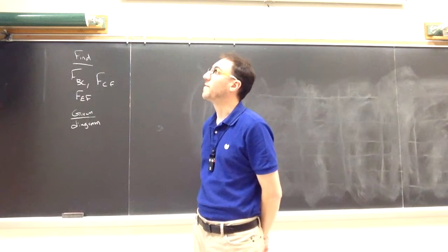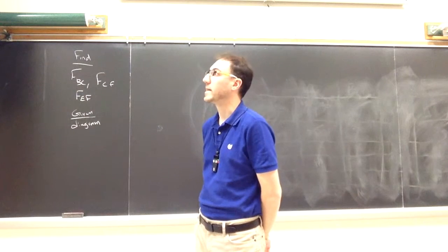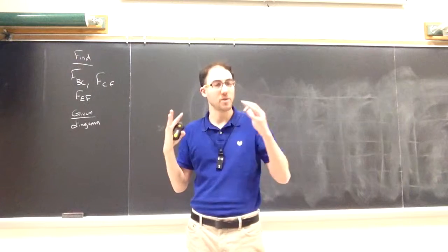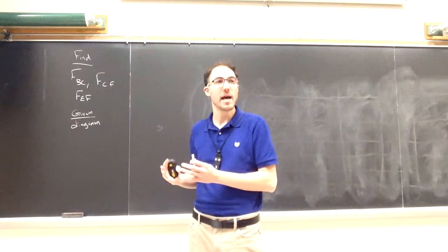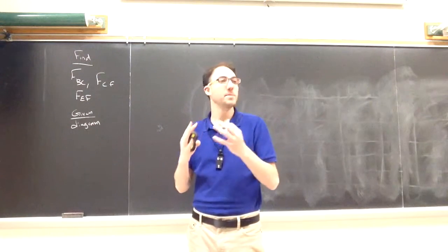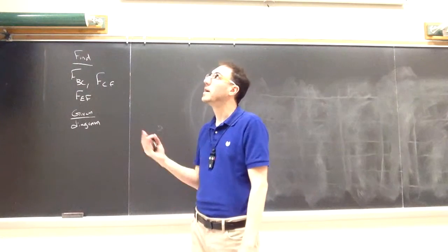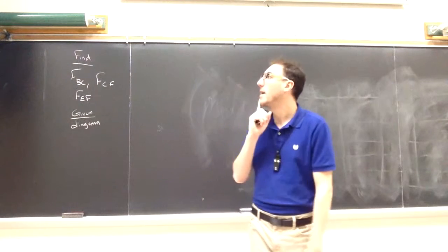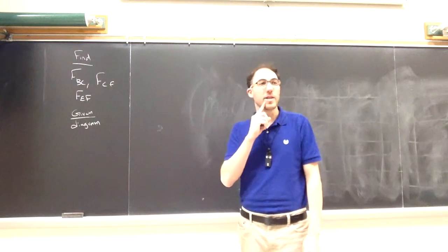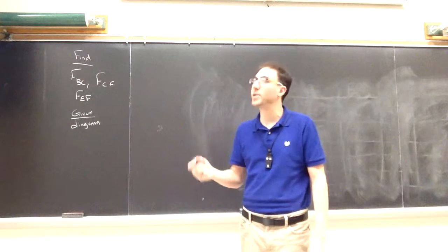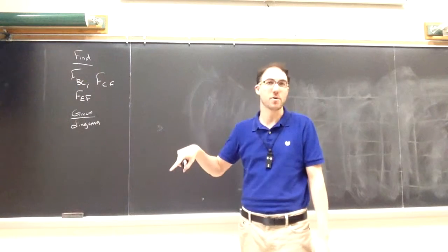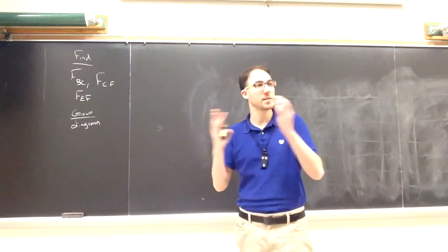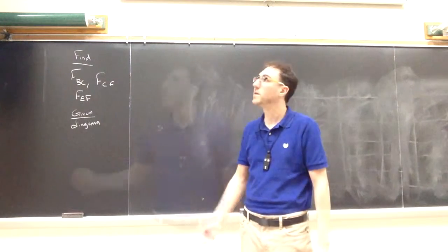In this case, we want FE, CF, and BC, which are kind of in the middle of the truss here. We're going to segment or section out this truss and analyze basically a subsection of the entire structure. Now this one's set up nicely. We want to know the force in BC, CF, and EF. So the idea here is, can we make one continuous cut through the structure, close it in on itself, and then keep everything on one side or the other of our cut?